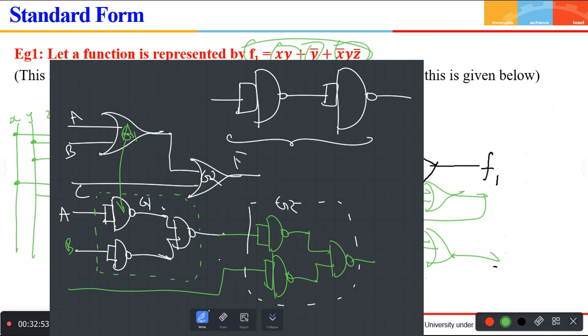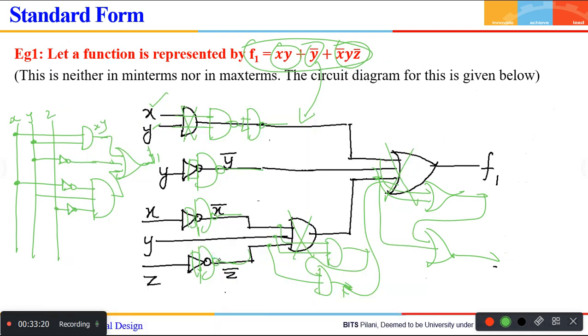When these two are coming in series, do we need to keep that? Why we don't need to keep that? Redundant, right? Why? Because if you give 0 here, 1 will come, right? And that 1 will go here, 0 will come. So do we need these 2 gates? Not required. Remove the redundant gates after replacing every gate by universal gates. Sit and practice this.